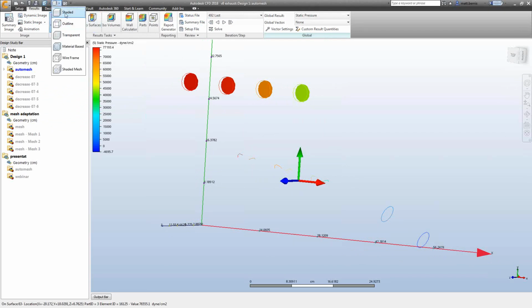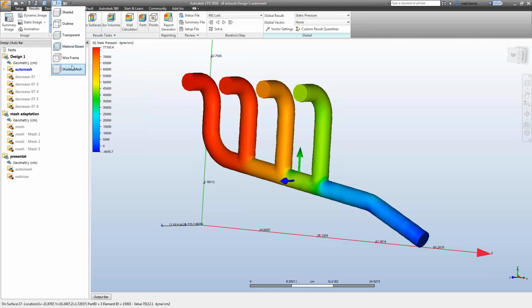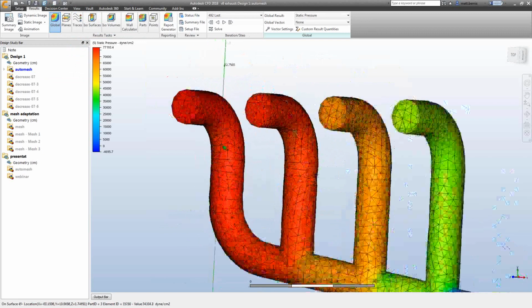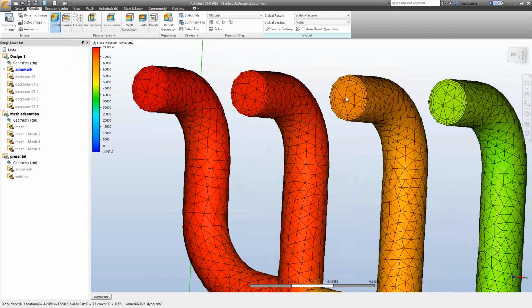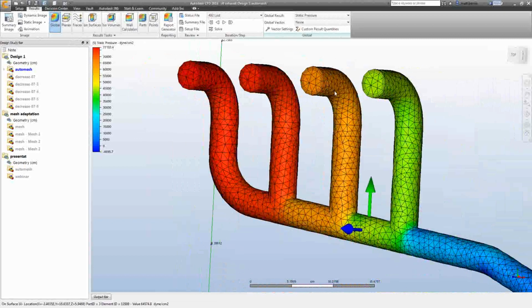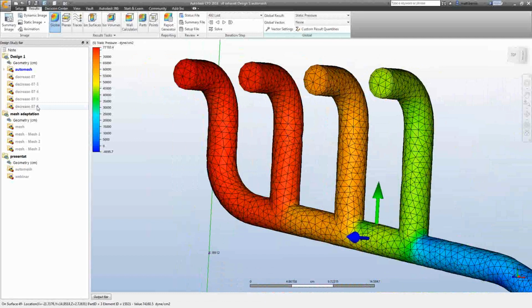So this is showing pressure, but the end goal here, what was kind of cool, is it'd be awesome if all these had the same pressure. Of course, this is a great representation. They're very different. You can see this is way too coarse. I mean, 3 elements across 4, I've seen worse, but in something like this where you're not sacrificing much for a lot better, and we consider these critical areas, you definitely want to add more.